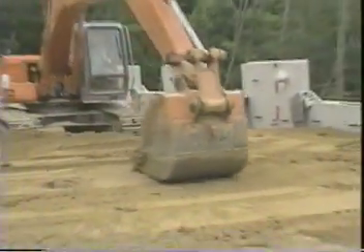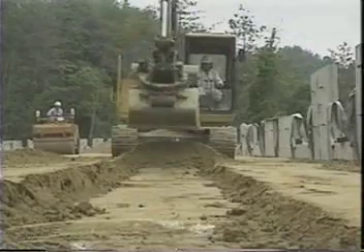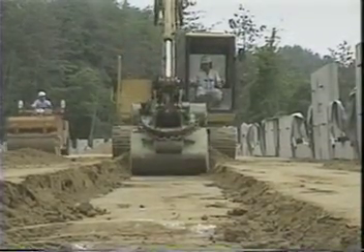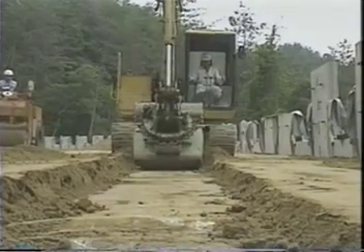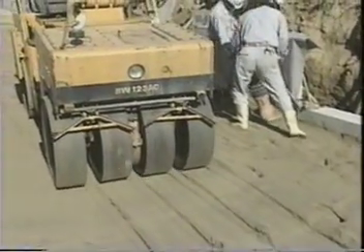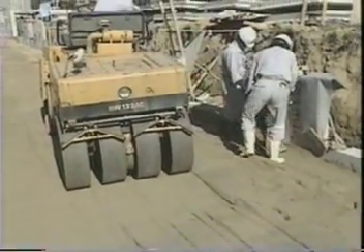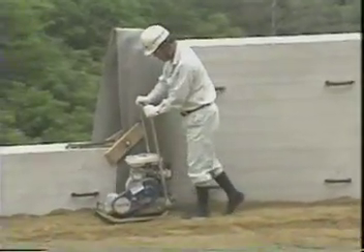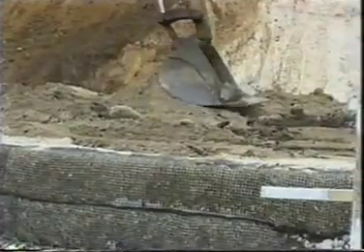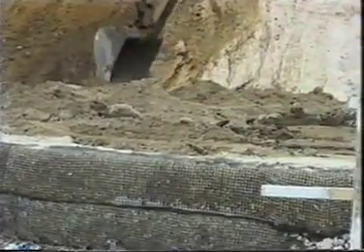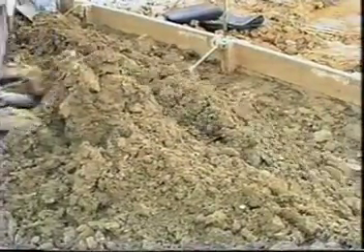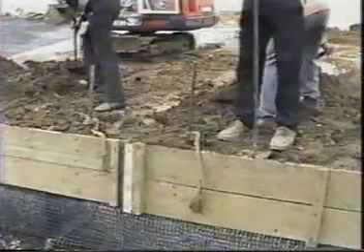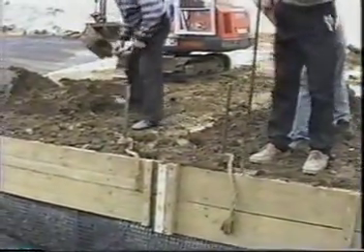For example, if the facing is a precast concrete partial height panel, a high grade of fill is needed to achieve the specified tight construction tolerances. A fine-grained soil with a significant clay content would tend to squeeze laterally and press against the facing. On the other hand, a slope with a wrapped face, with more relaxed construction tolerances, may allow adequate compaction of a lower grade of fill.